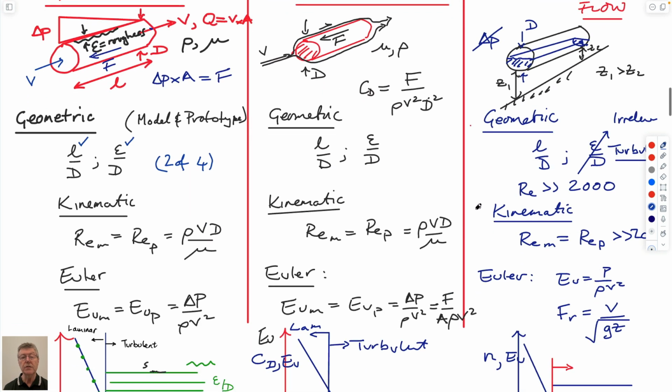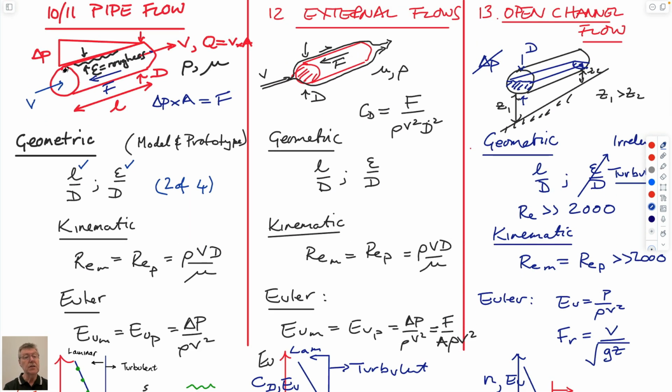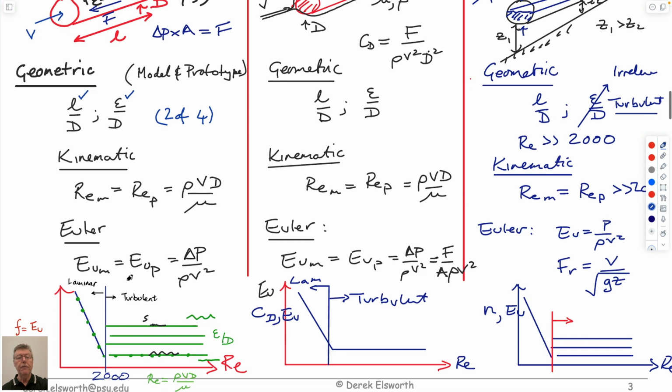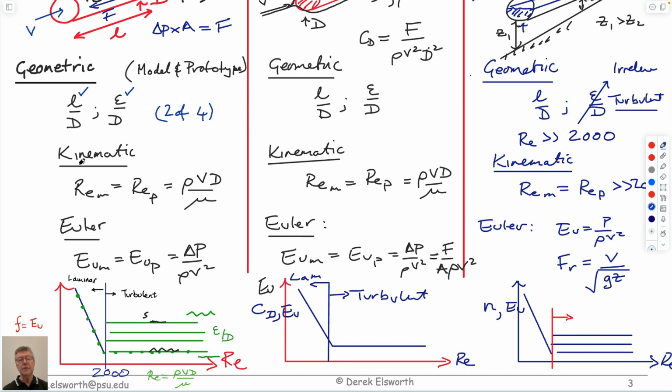And so the appropriate force that we're applying in the system is just the pressure upstream and the pressure downstream, and they'll be different from each other because we're using up energy in the system, which is the viscous drag on the side of this, which is the other part of the system. And so we'll find out that the behavior of the system is given by these variables.